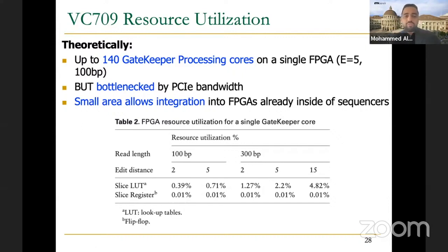That, of course, if the critical path allows for that. You may want to pipeline these problems together because the maximum delay you can have cannot achieve the maximum frequency you can use in the FPGA. So the critical path in FPGA implementation is very important here, so that you can drive a lot of these